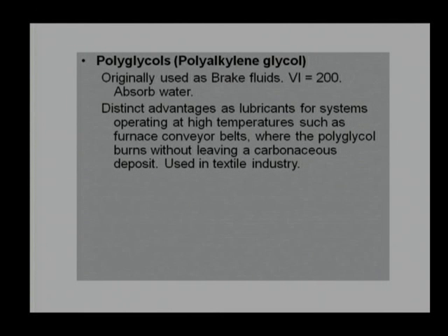We ran that setup at 6000 rpm for almost 3 to 4 hours, and we found not even a single degree temperature rise. The reason being, magnetic levitation was there, and even though there was a problem created for the hydrodynamic action, there was clear separation between those surfaces. So, for high speed applications, this kind of oil can be utilized. They have very low viscosity, which is always desirable for high speed applications.